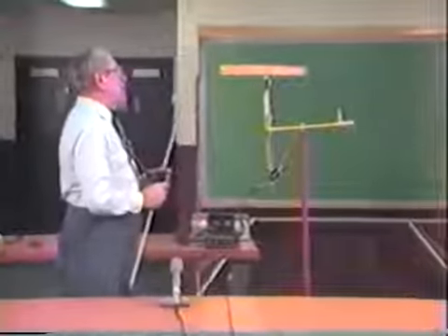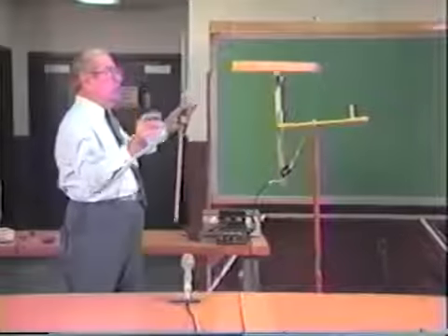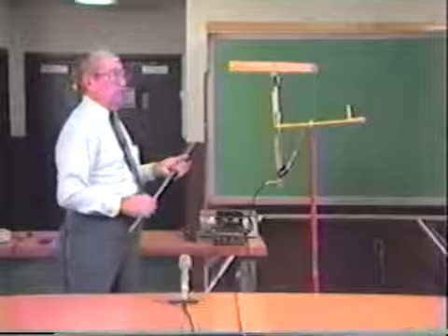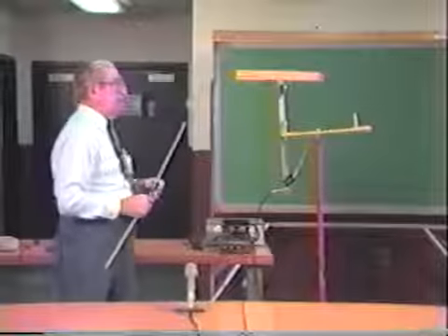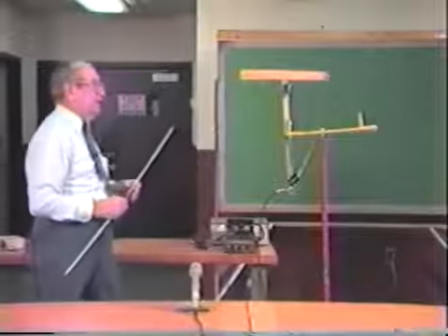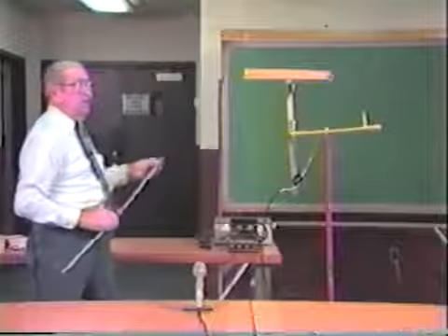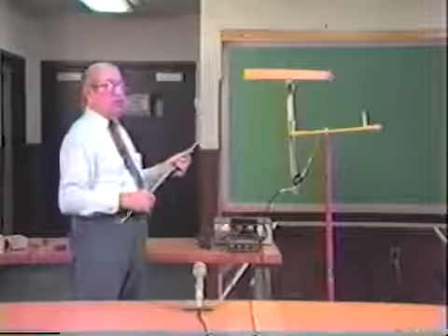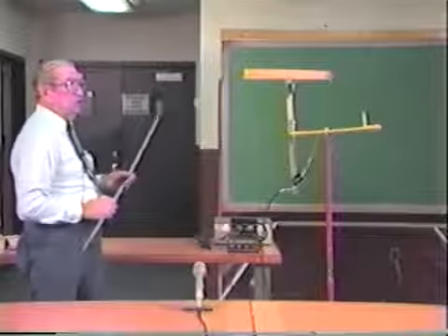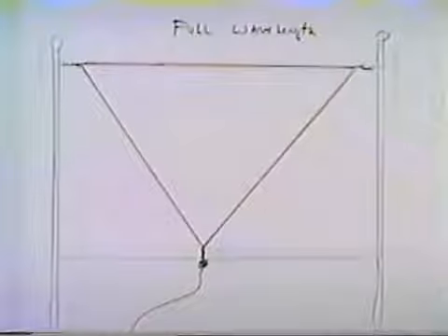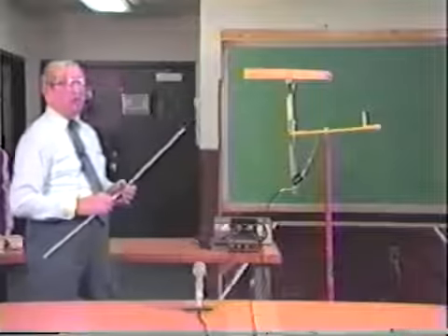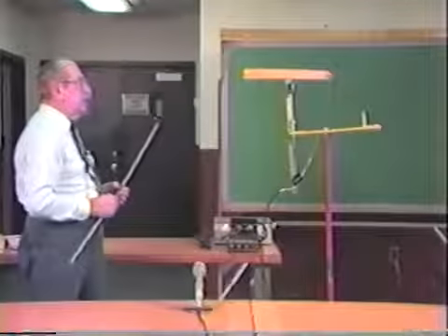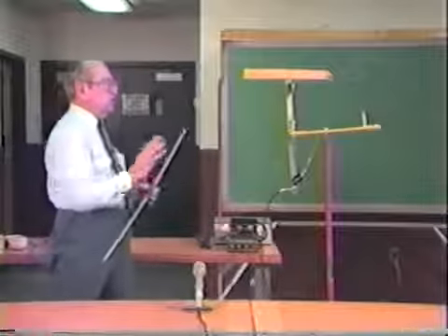It was developed primarily because it's easy to support, particularly on the lower frequencies where we're dealing with 4 megahertz or 7 megahertz, where you have antennas that are in the 120-foot range or in the 66-foot range, where this could be strung between two trees or two supports. And it's a very effective antenna and a good antenna. And we thought that in view of the demonstration, we should put this into the comparisons between antennas. So much for the delta loop.